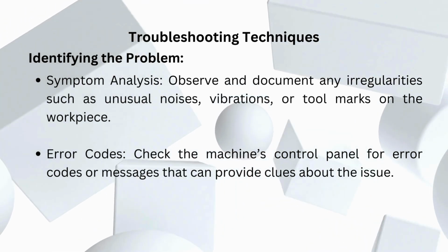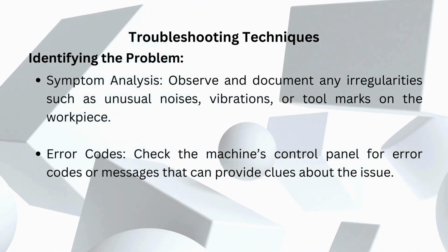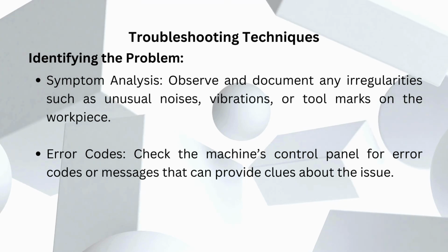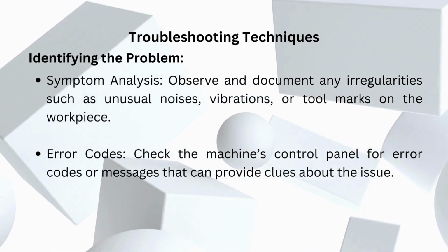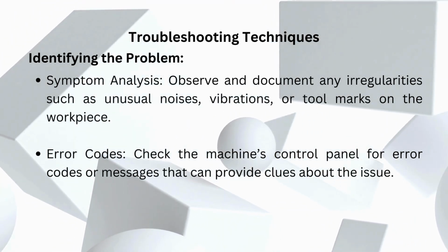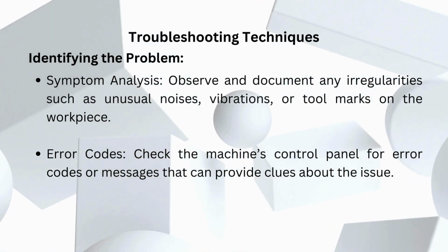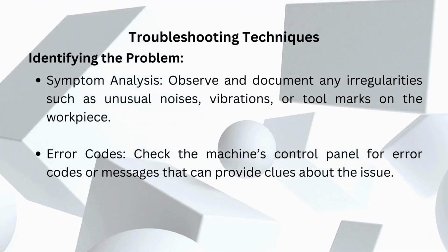Troubleshooting techniques. Identifying the problem. Symptom analysis. Observe and document any irregularities such as unusual noises, vibrations, or tool marks on the workpiece. Error codes. Check the machine's control panel for error codes or messages that can provide clues about the issue.